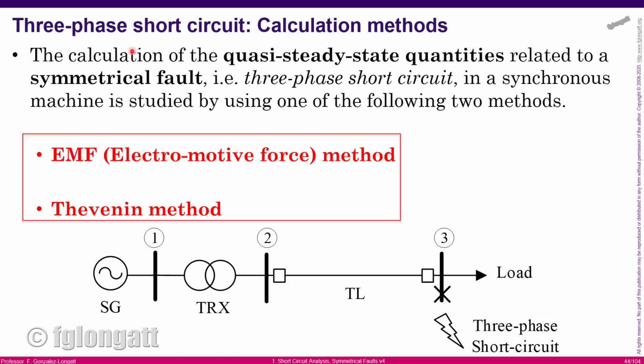And in each one of them, I can use phasors because I assume that the inductive reactance of the synchronous machine is constant in that period, okay? That is the most simplified way. This assumption allows me to use phasors and simplify the calculations, avoiding the differential equation, okay?